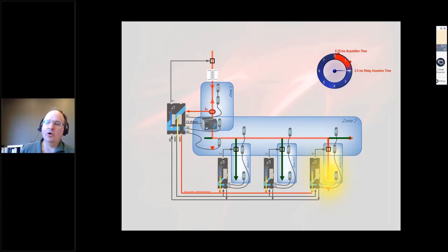At the 2 millisecond mark, the relay asserts. So it has now seen more than 50,000 lux of light. And if you look at the current transformer as well, it doesn't even wait for the peak of the sine wave. It sees di/dt, a rapidly changing current with respect to time. At the same time, it sees the light. Okay, I'll run this again. Two millisecond assertion time, and now the relay asserts.